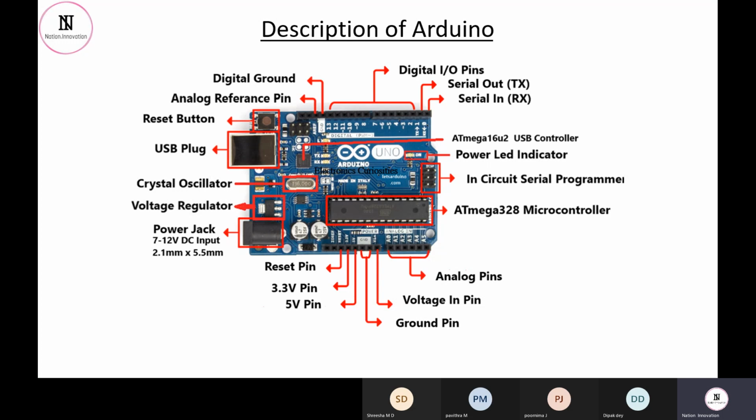What are the different things available in the Arduino? The main first thing is your Atmega328P microcontroller, which is basically the brain, the main body of the Arduino. This is where your code is going to be stored and where the logic will be coming. And to run this board, this crystal oscillator over here will be used, and it's a 16 megahertz crystal oscillator. Fine.